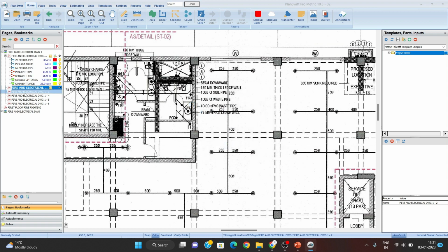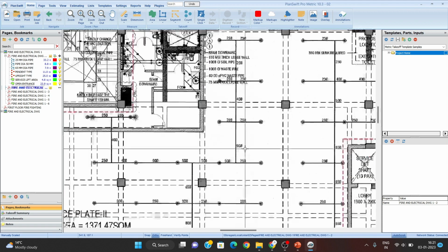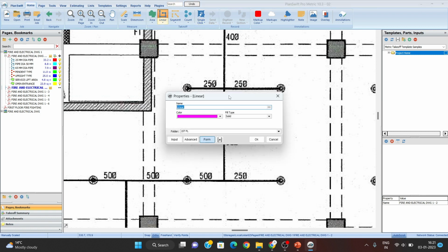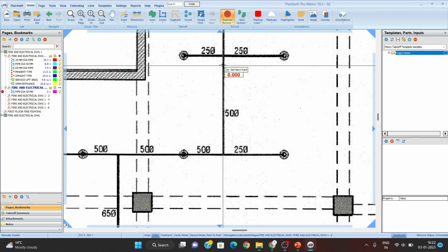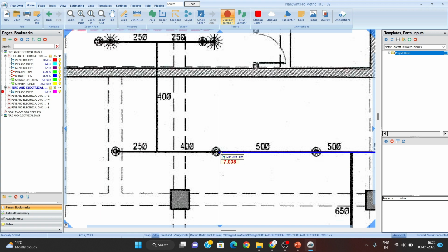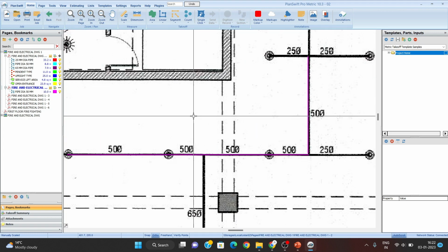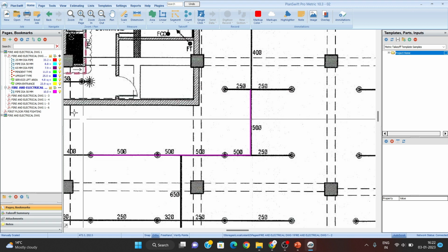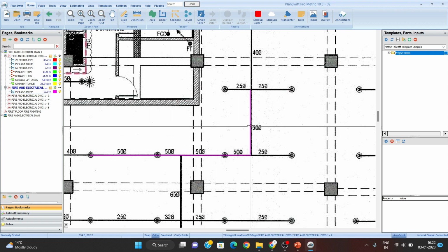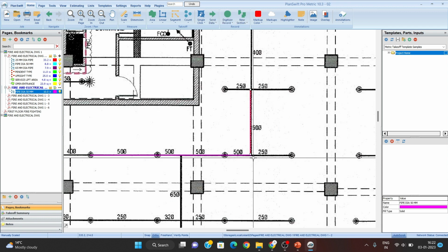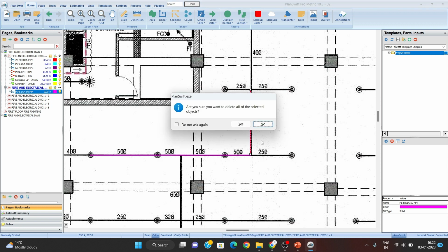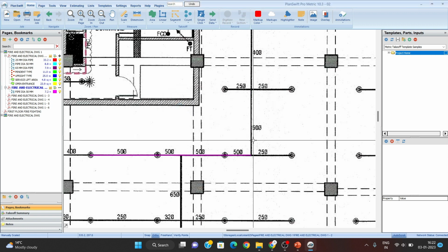Now if we select anything from here, for example, if we take 50 dia linear pipe, pipe dia 50, okay, first row is already selected. See, 50 dia pipe. Okay, for example, we have taken this one. If we want to delete whatever we have taken, we can delete it separately also, like this. Press here, see this much is selected from here to here only, and if you want to delete, press the delete button from your keyboard, and yes, only this much will be deleted.